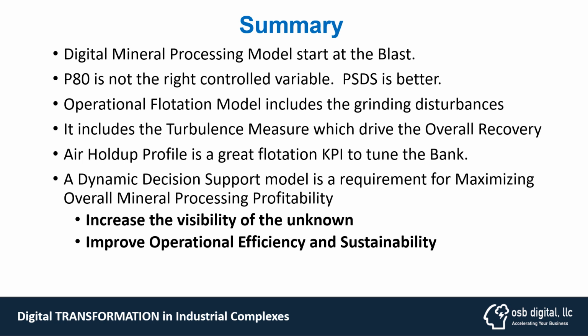Very important. So the P80 is not the right control variable. The particle size distribution shape is much better, using this hybrid simulation model in real time, and also the Gaudin module that enabled us to understand the two slopes on the grinding circuit, and really assess what we need to do.